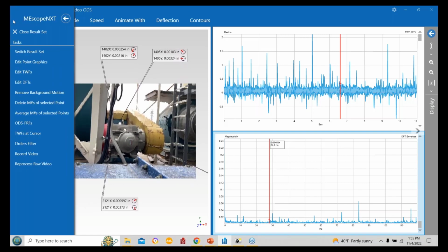Any other questions? Just a comment, Marion mentioned it's nice to show orbits and mag phase on the same points. Yeah, it is, for sure. If you have some additional questions, feel free to go ahead and type those in. One thing, different directions: right now we're looking at the side of the machine from a little bit of an oblique angle, but get another one going axially to the motor and you'll see a lot of different motion all in the same machine.